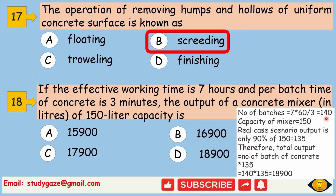So in total 140 batches will produce the concrete, and capacity of one mixer is 150 liter. In real scenario output is only 90%. So 90% of 150 is 135 liter. Therefore total output is number of batches into 135, that will give you 18900 liter. So the option is D.